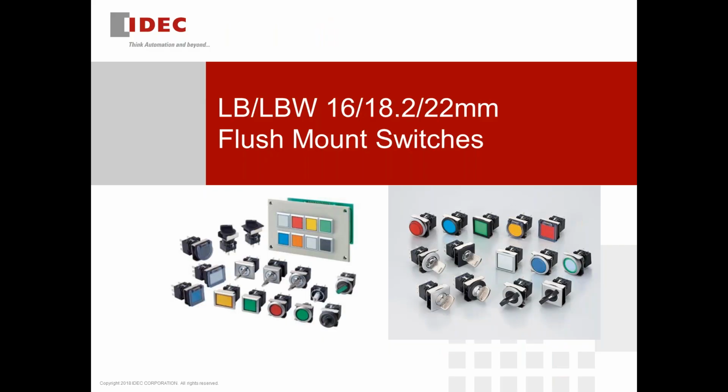For the rest of this session, I'm going to focus on LB/LBW. Again, we have lots of choices, lots of functions and features to choose from. LB and LBW are basically a brother series. They share the same 5 amp contact block, but the operator size of the LBW is bigger. And the panel cut size is also 22 millimeters versus 16 or 18 millimeters.